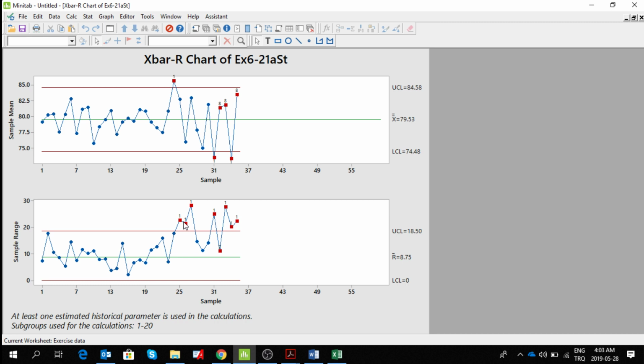So we have the test results. In the test results, it's gonna show how many points have failed. 1, 2, 3, 4, 5, 6, 7 numbers. 7 points failed. Let's check which sample this belongs to. This is sample 25. Let's check that. This is sample 24. Okay. So if we look at the first R chart, 7 points have failed. So we close this.